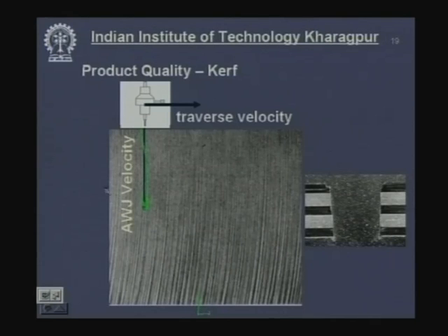What can you see in the longitudinal section? The upper part is rather smooth, the surface is very good, but in the lower part you have a lot of marks. Can you see them? And they are periodic. So, the mechanism of material removal would be different. If you require the surface to have smoothness, then you have to set your parameters accordingly.